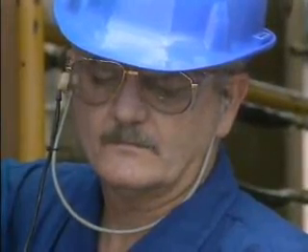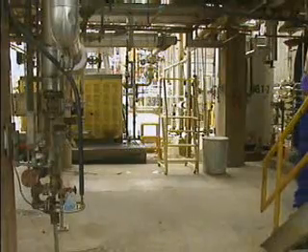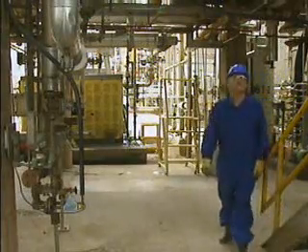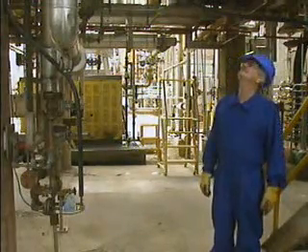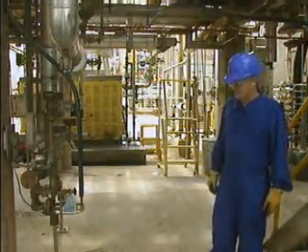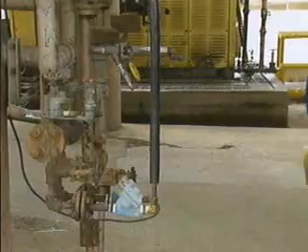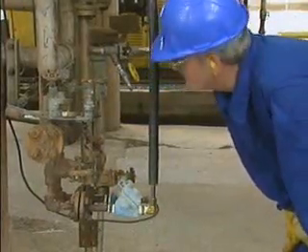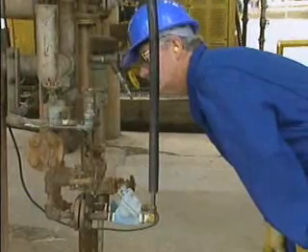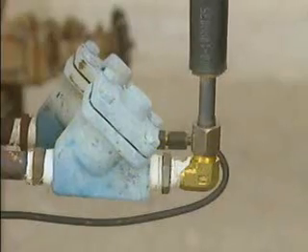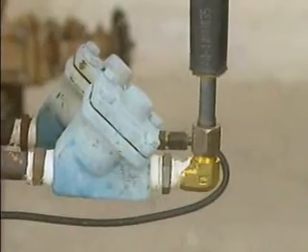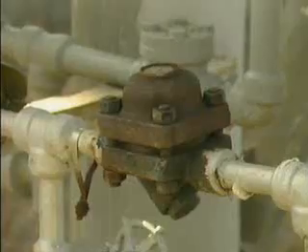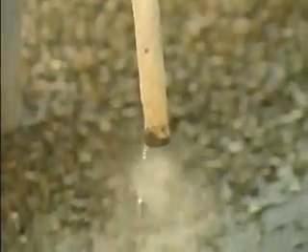A visual inspection can be a very informative part of a steam trap survey. But as with other types of inspections, you need training and practice to be able to perform the inspection effectively. Begin by simply looking over the trap for condensate or steam leaks. Leaks typically occur at piping connections and at the steam trap's body-to-bonnet connections. Next, see if live steam is being discharged from the trap.